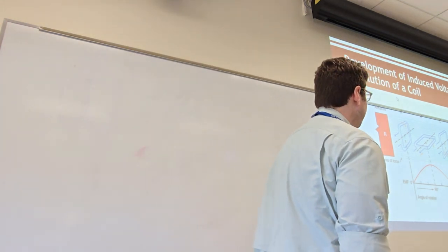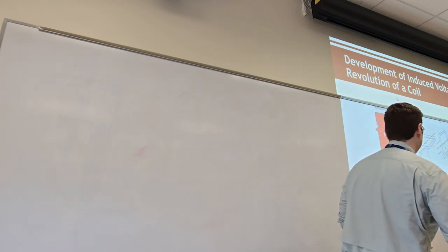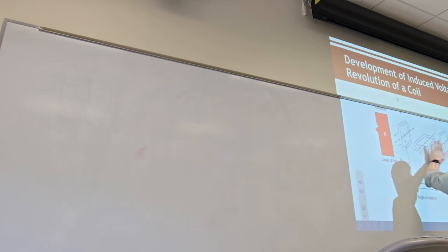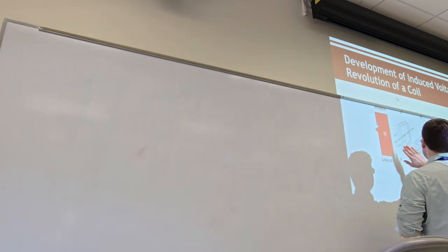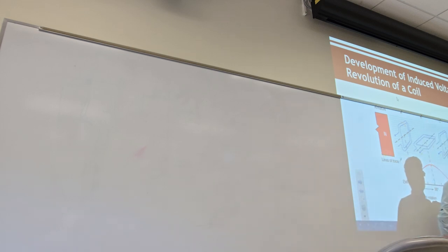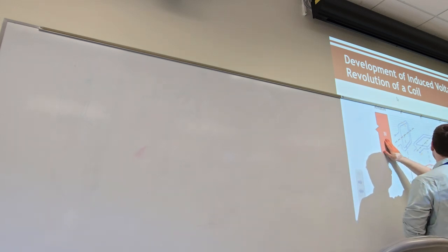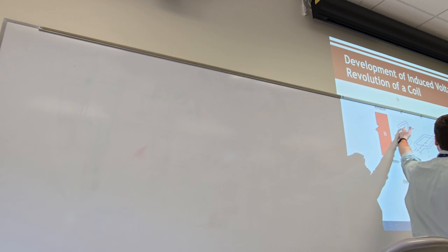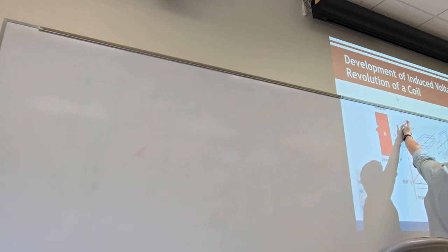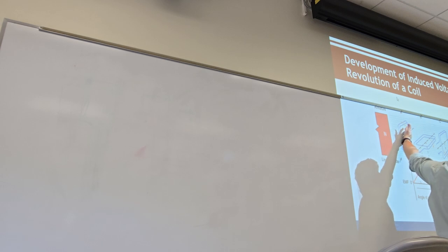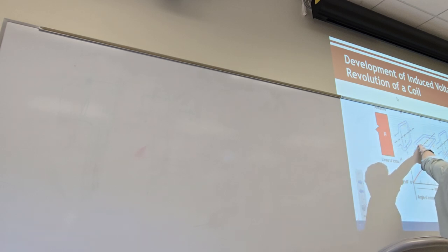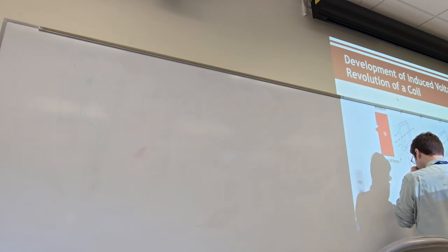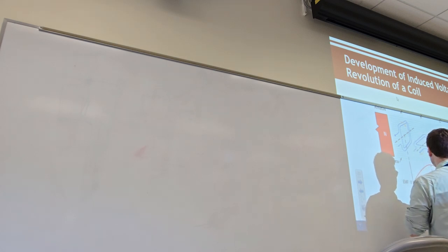Coils come in many shapes and sizes, but they afford certain advantages. One of which is that if we have a so-called straight magnetic field, where it's very well aligned, so the magnetic field lines are very straight across our two plates, our north magnet and our south magnet, and we rotate or place a coil within that field, oriented this way, and then turn it so it's oriented this way, this is the EMF, the voltage, the electromotive force that we see as a result of that rotation.